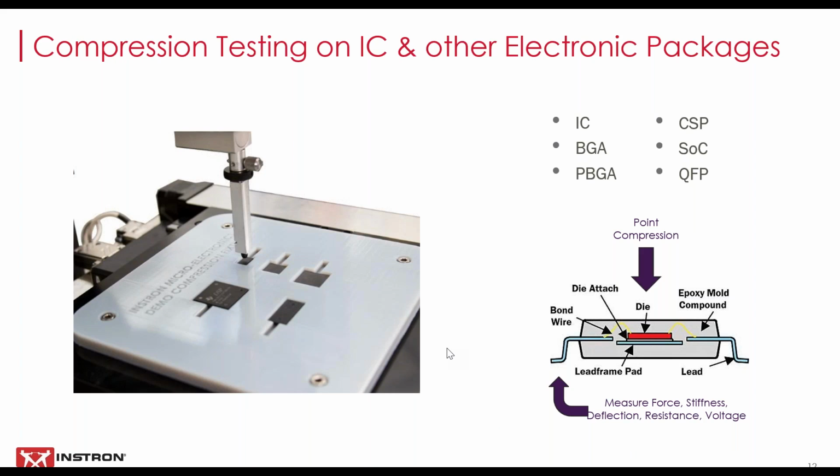We watched a video of this application earlier. This is a multi-point compression test that is performed on integrated circuits and other electronic packages, such as ball grid arrays and chip scale packages. A compressive load is applied to measure deflection and stiffness. The corresponding voltage at that load is measured as well. That stiffness and voltage data is used to compare various chips and to qualify new materials and forms.